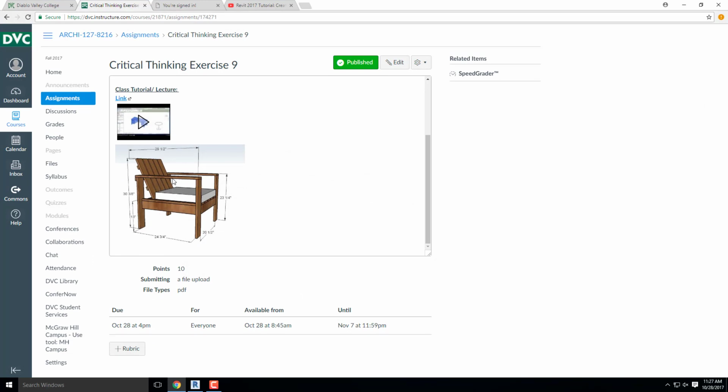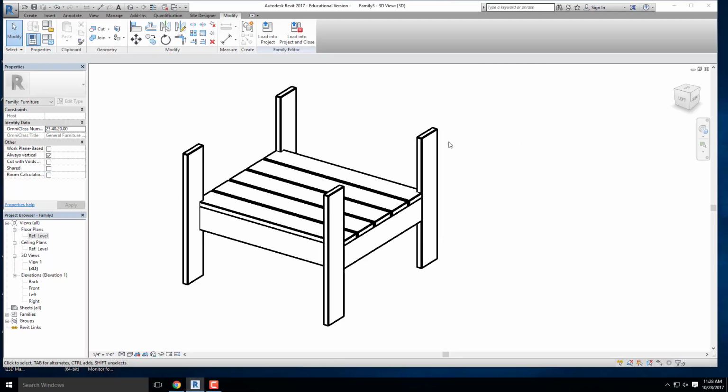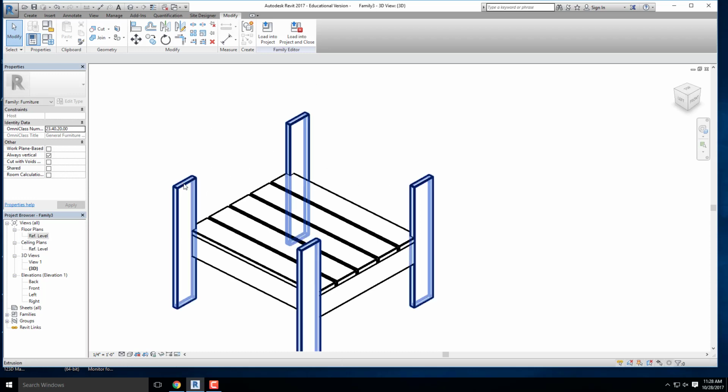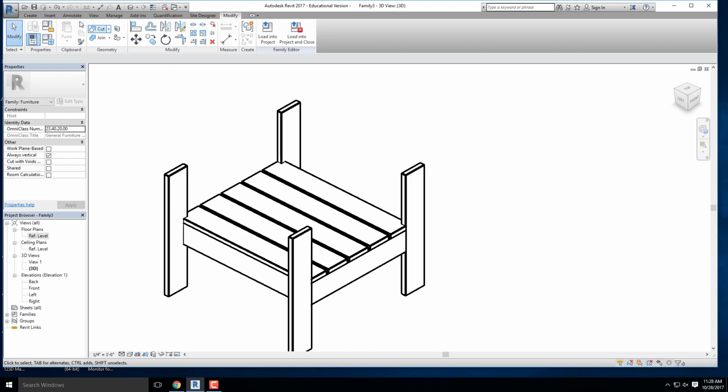So now let's build the arms. Okay, the arms are going to span the entire width of both of the legs plus what dimension? 3/4 of an inch. It goes over by 3/4 of an inch because it has a little support here on the back. Okay, so I am going to change now so that I don't keep adding dimensions on top of my reference plane. I'm going to change my reference plane to the top of these arms so that I don't have to keep adding 3/4 of an inch increments on top of all of the extrusions that we did.